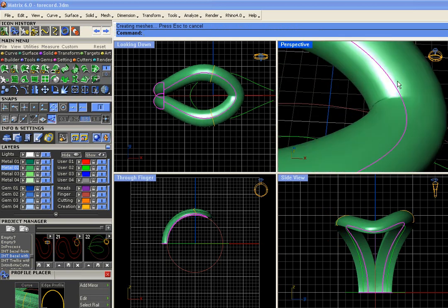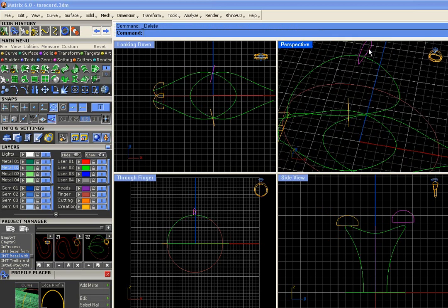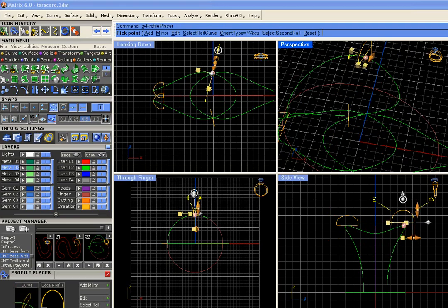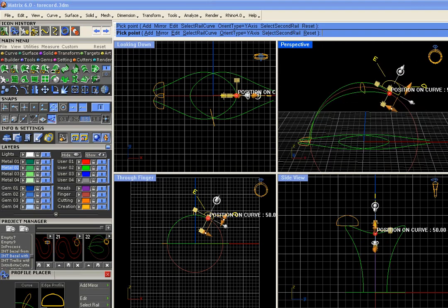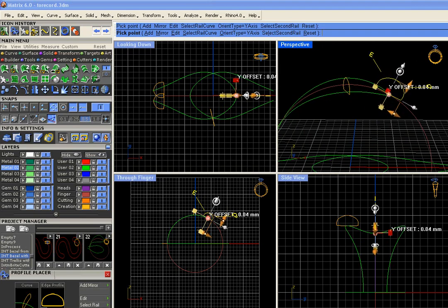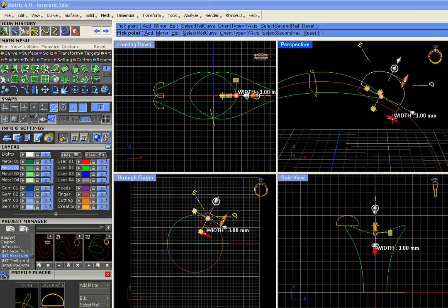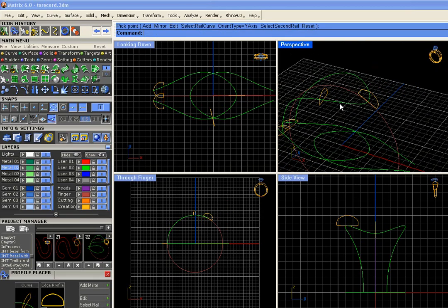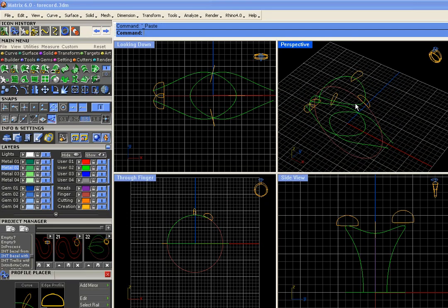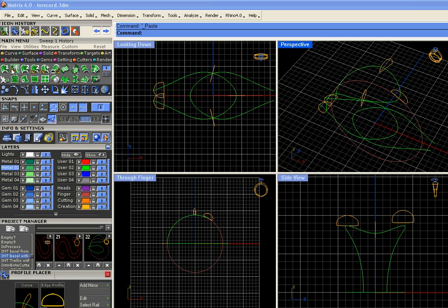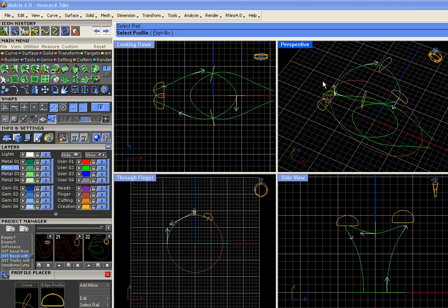Now if we have a kink here, let's throw away that surface and add another one. F6, MSR, and go ahead and add this guy right here. He can obviously come down and touch, and can be whatever height you want him. Oops. If you did what I did and you took him away instead of hitting add, don't know how I did that, but copy it in position, hit undo, and then paste it, and it'll go right back where it came from. Okay, we'll sweep one again because we added that profile.